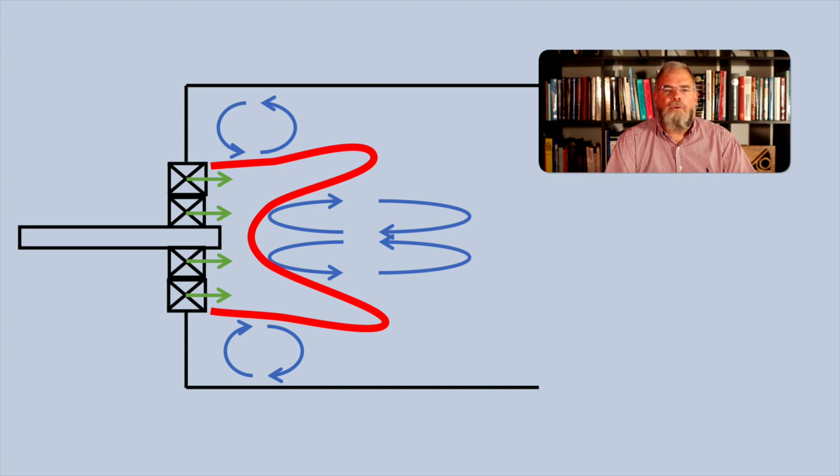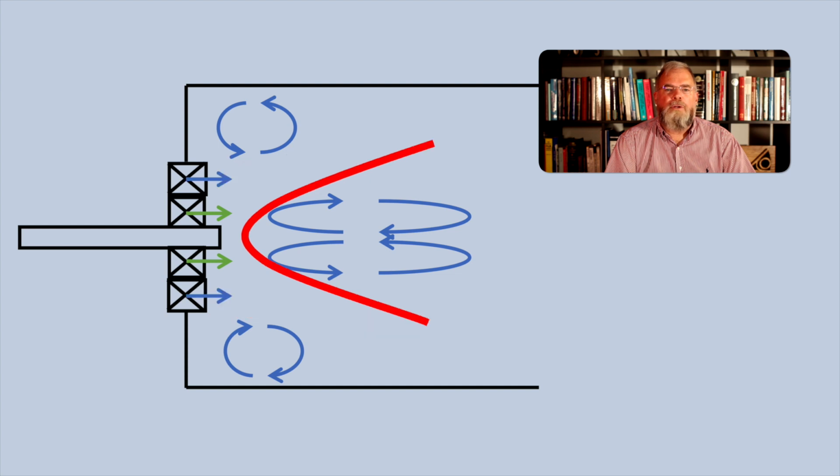As load is reduced, the fuel to the outer swirler is switched off. This leaves only the flame, which is stabilized by the central recirculation zone. An advantage to this approach is that flow from the outer swirler, when it no longer receives fuel, will not have a direct impact on the flame stability of the flame attached to the central recirculation zone, as the central recirculation zone is fed hot gas from its own flame.